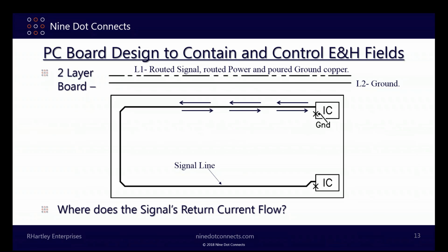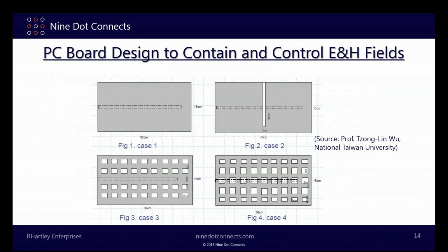Basically these arrows are showing, the arrow pointing to the left is showing the forward current, the arrow pointing to the right is showing the current in the return plane directly underneath it. And the energy would just move around the trace from one side to the other. The return current would stay under the trace in all cases.